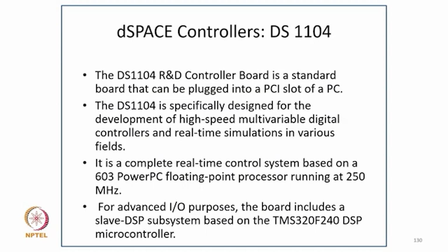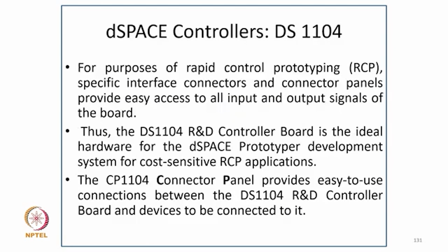It is a complete real-time control system based on a 603 PowerPC floating point processor running at 250 MHz. For advanced input-output purposes, the board includes a slave DSP subsystem based on the TMS320F240 DSP microcontroller. For the purpose of rapid control prototyping, specific interface connectors and connector panels provide easy access to all input-output signals of the board, and thus the